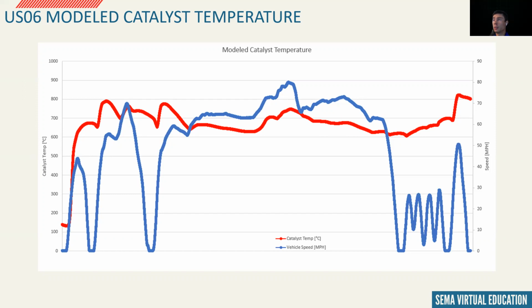Ideally, the correct threshold and enrichment targets during COT are values that normalize catalyst midbed temps to no more than 900 C. If you want to go higher than 900 C, you should have testing to support this. It is not suggested.